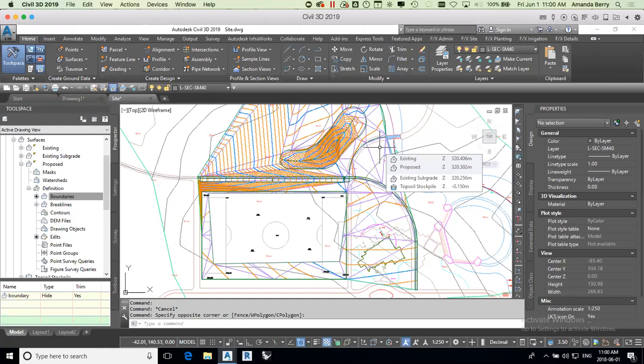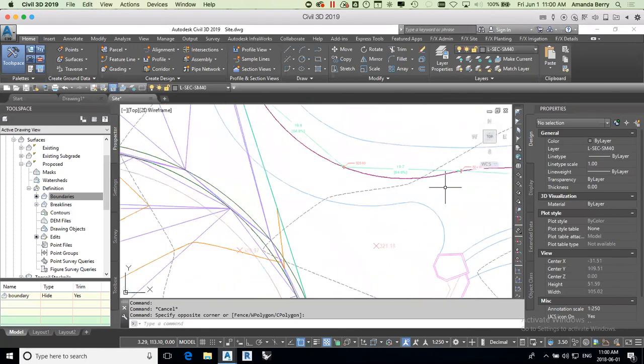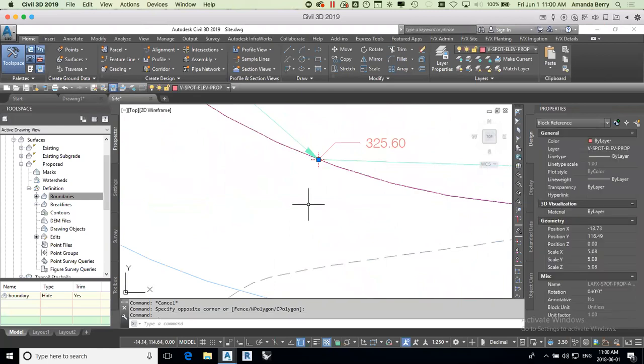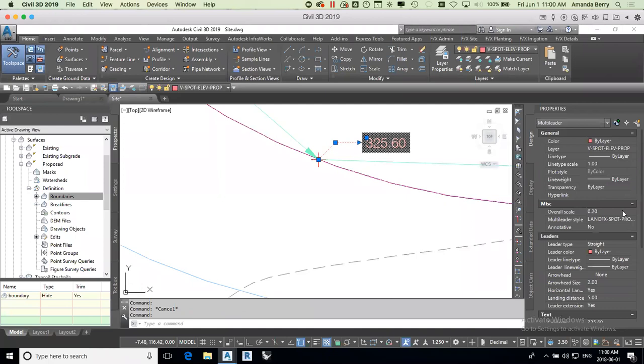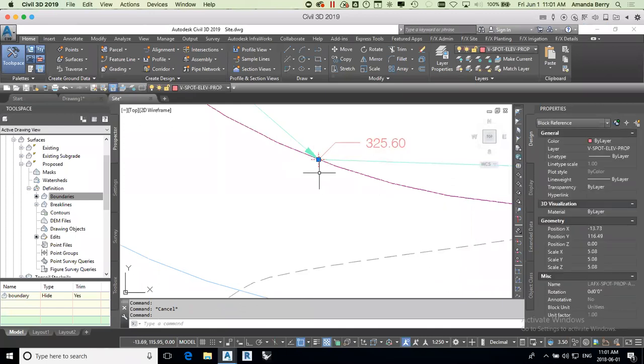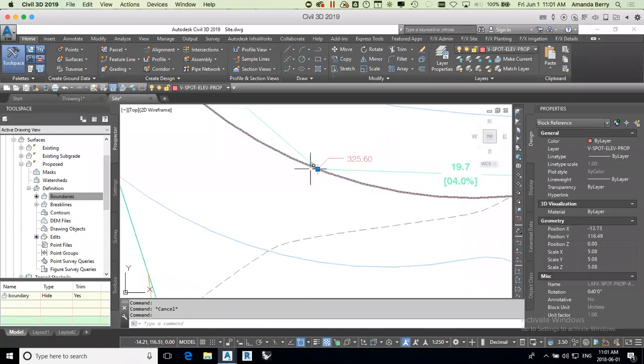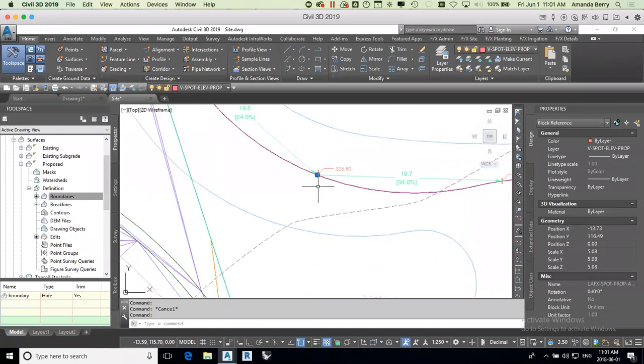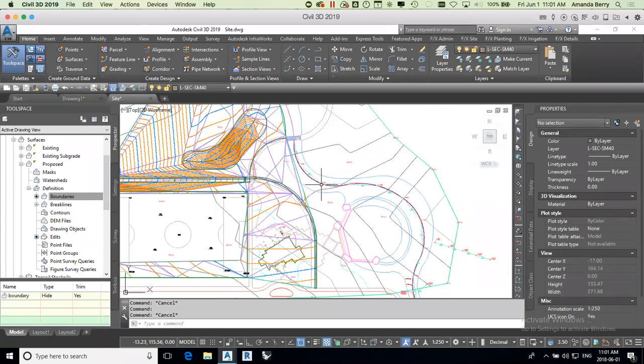Perfect. And then one last question. Stephen was just saying, he uses Civil 3D quite a bit, and he was wondering if there's a way to use the Land Effects spot elevations as points in creating the Civil 3D surface. Let me see if we added that in, Jer. No, these do not have a Z position. I believe that is on the wish list, if I'm not wrong. It's already on the wish list to add an elevation to that spot in order to eventually use it. But in order to quickly add it in, you would need that spot. However, it's really easy to just add your own spots.